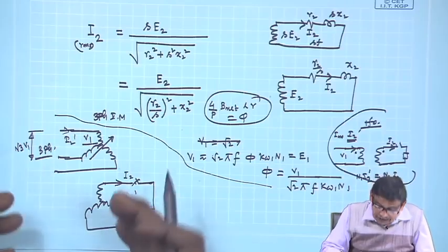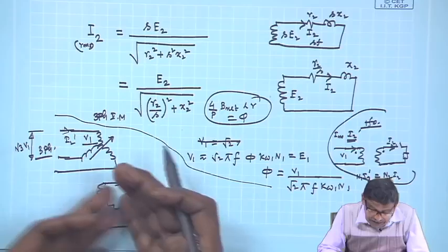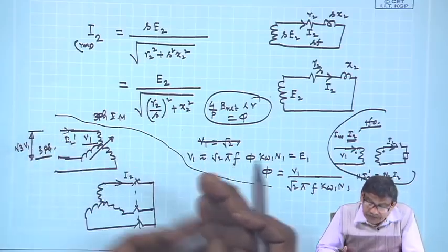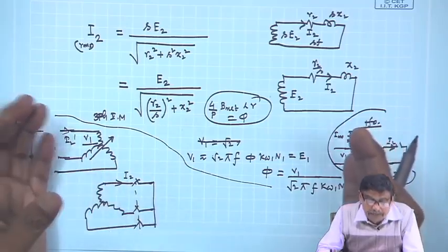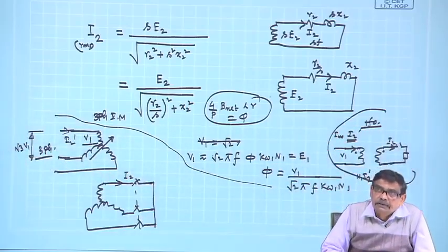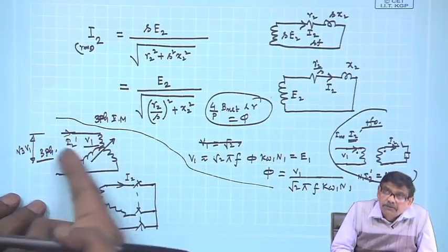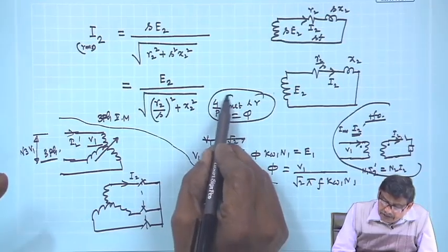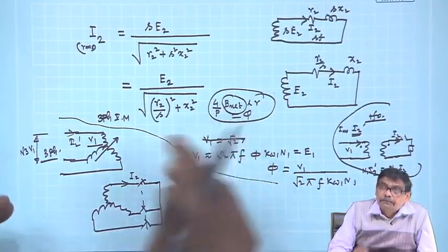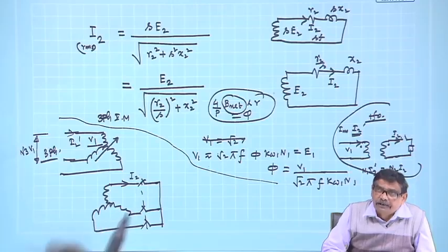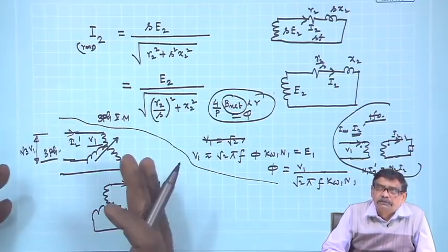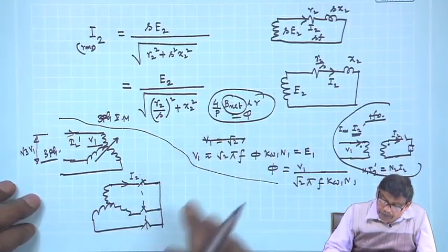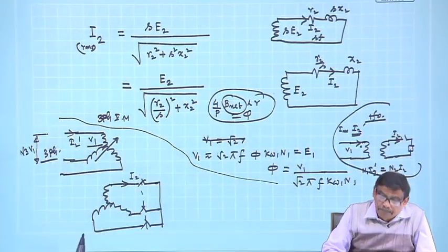That is how, when any current is drawn on the secondary side of a transformer, primary current is automatically increased, because it has to satisfy the KVL equation here. Therefore, remember this B net value remains fixed in magnitude. Its position may change from one place to another, that is a different issue, but flux per pole is remaining the same.